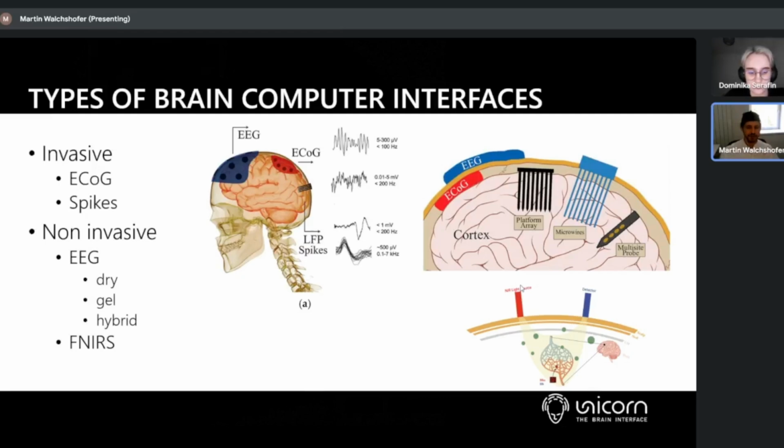And there are some differences with light-based BCIs. You have a slower time resolution. Like it takes some time until blood flows into a brain area and the oxygenation rises. For the EEG, we measure the electrical potentials, and that's working a little faster, and it's a little bit more responsive. And for EEG systems, we also have a couple of different possibilities.